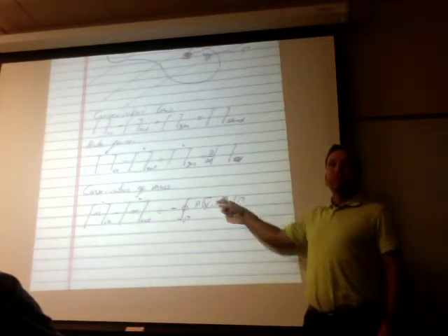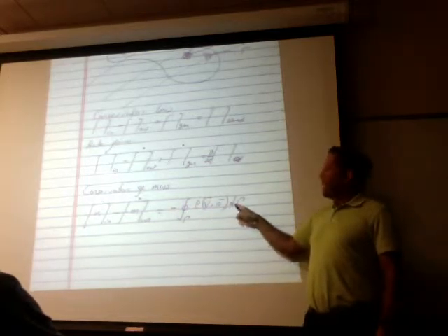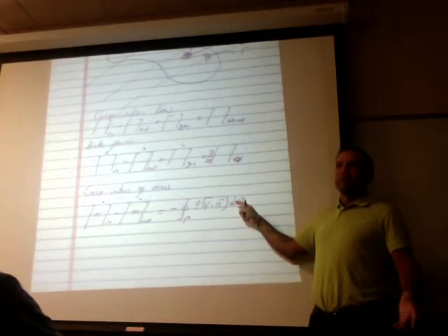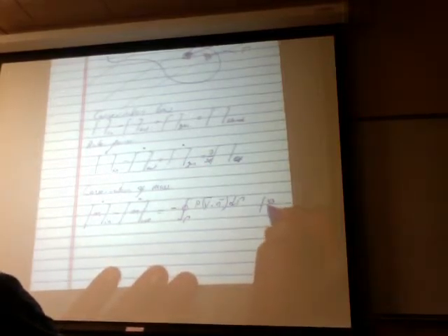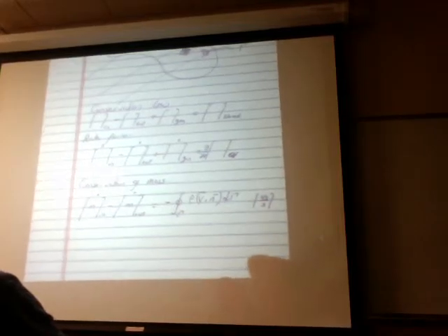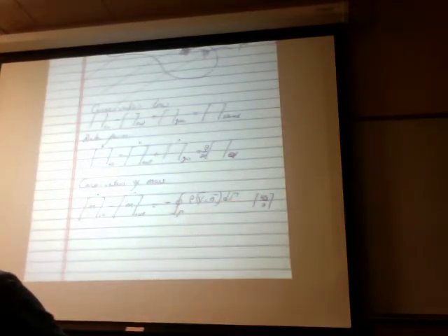Why is this the mass flow rate? Well, we have density, velocity, area. That's mass flow rate. Okay? So that accounts for the net amount of mass entering and leaving the boundary. And this is in kilograms per second. As you can see, if you use SI units, that would be density, velocity, area.